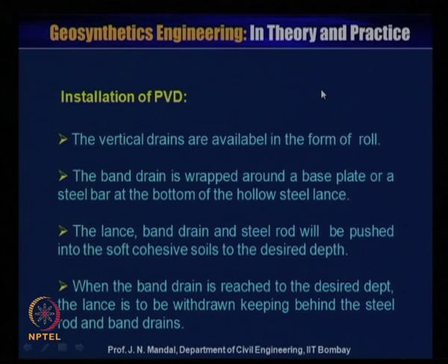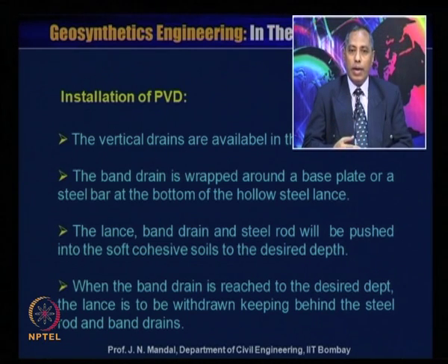So installation of PVD, the vertical drain, is available in the form of a roll. The band drain, or the prefabricated band drain, is wrapped around a base plate or a steel bar. I will show you later what that steel bar and the base plate at the bottom of the hollow steel lance are. The lance, band drain, and the steel rod will be pushed into the soft cohesive soil to